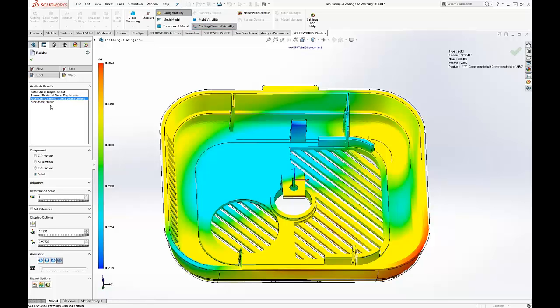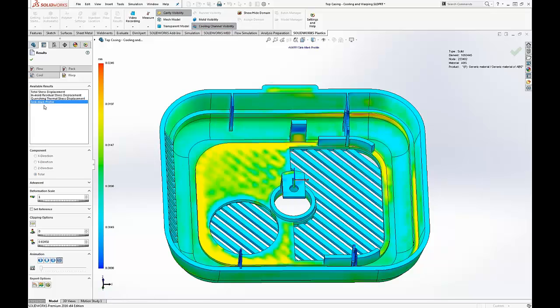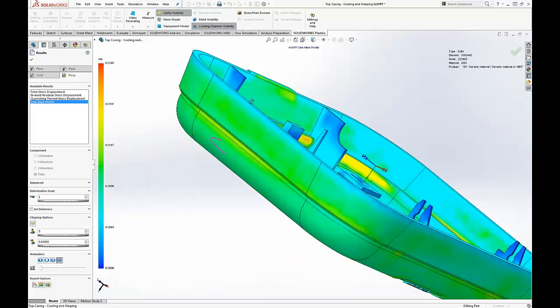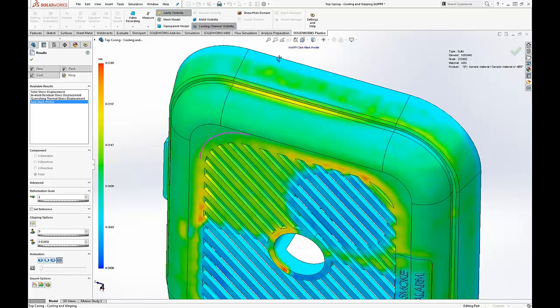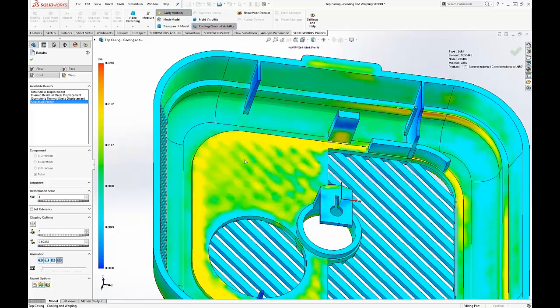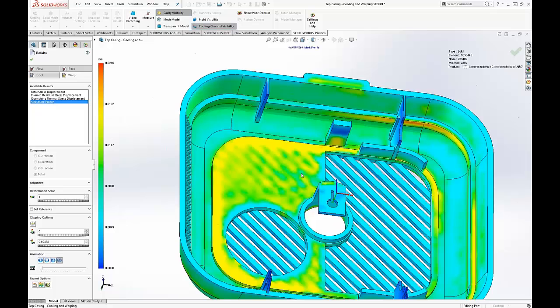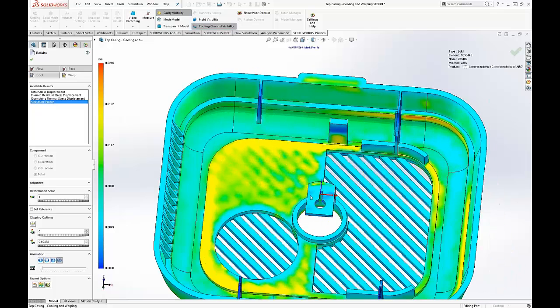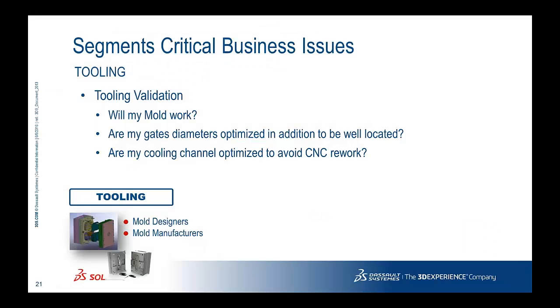Another thing that is really important to see again is the sink mark profile, because the sink marks are calculated also in the filling phase and in packing, but here they are far more precise, so you can see the final value. So here you can better evaluate which are the final problem areas from the sink marks point of view. Let's say, briefly.